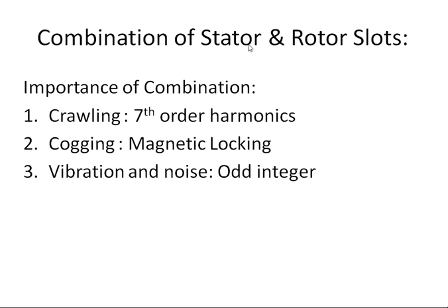So this combination of stator and rotor slots will decide the value of the torque or output power available to the motor. So we must be in a position to select a suitable combination for the stator and rotor slots, which is the objective of this lecture.